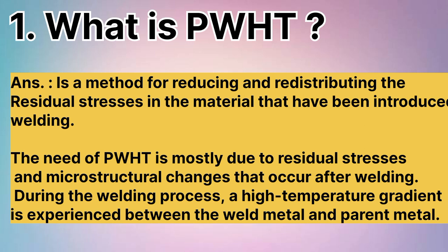ASME Section 8 Division 1 specifies the PWHT requirements for material used in equipment designed as per ASME tables UCS 56-1 through UCS 56-11. ASME Section 8 Division 1 provides heating cycle data required for PWHT of material based on P number and grade number, which is categorized in ASME Section 9. Those tables are followed by notes which provide exemptions.